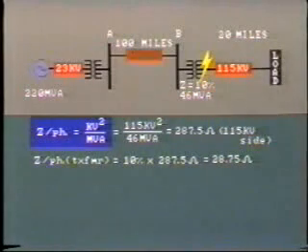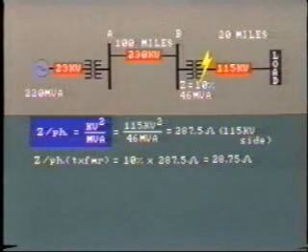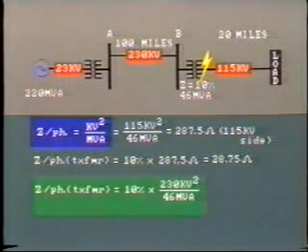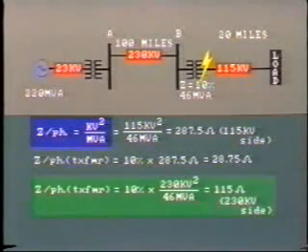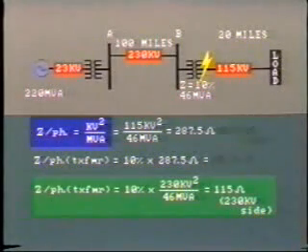But wait a minute, we may just as well have inserted the 230 kilovolt value for the transformer voltage instead of 115 kV. In this case, the ohmic impedance would come out to 230 kV squared divided by 46 MVA times 10% equals 115 ohms. This is an important conclusion. The ohmic impedance of the transformer is much lower when measured or seen from the low voltage side. This means that in order to add the different impedances in the system or perform calculations, we'll have to do a lot of number crunching as we go from one voltage level to another.